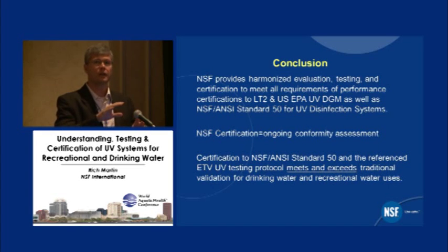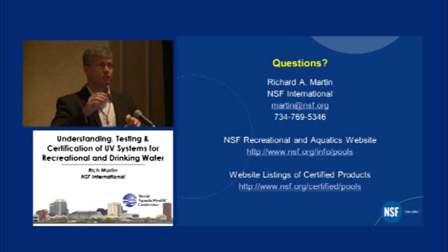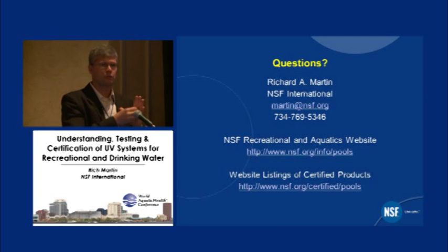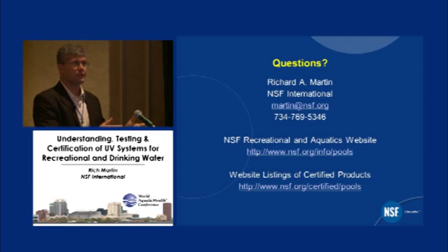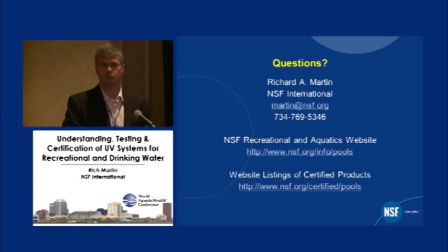So it is part of the testing program to test at different UV transmissivities. You do that to make sure that you can still function and provide a certain level of irradiance. That's a quantitative value, essentially like a power value. But that then translates: if the system is running with this irradiance and it generated a 3-log kill or a 40 millijoule reduction equivalent dose, those are some of the variables you need to make sure that you, as an operator, are getting that same level of irradiance at those flow rates. Then you're assured that you're getting that 3-log or 40 millijoule type reduction equivalent dose.